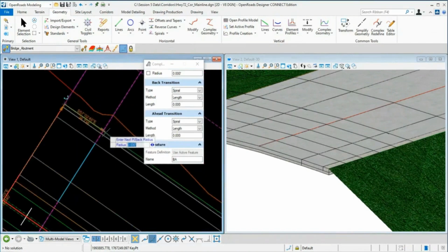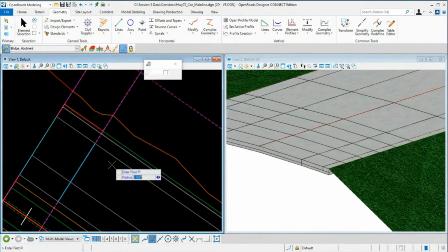And then over here, to finish this off, I'm going to go back to my intersection snap. Let's select this cyan line here. I'm going to move my cursor over to the template geometry there, that top of slope line. You'll see the intersection icon there. Lock into that location, and then you can just left click to accept. And then you can right click to complete. Okay.